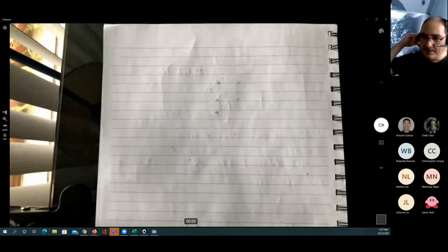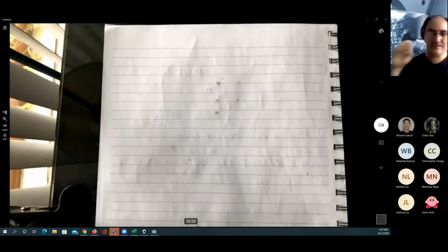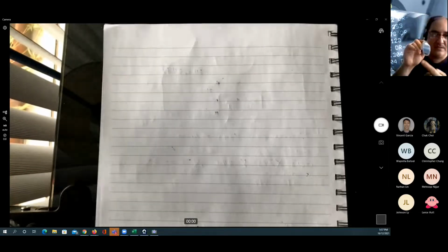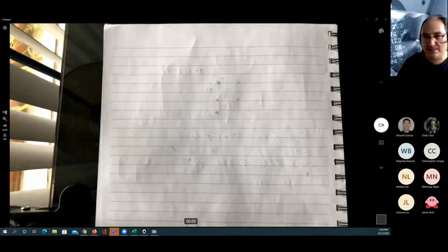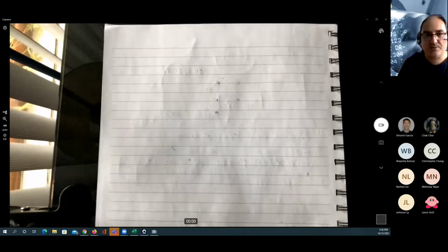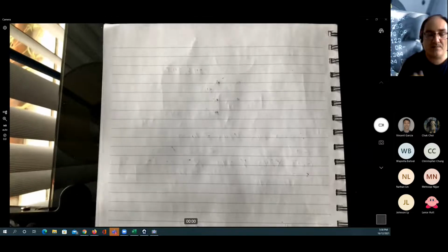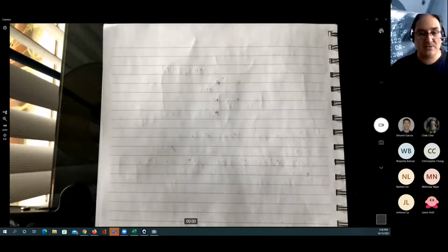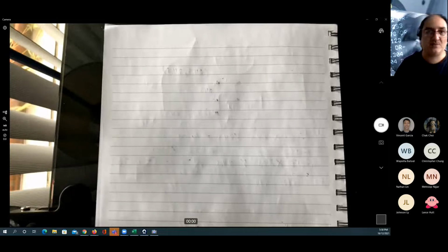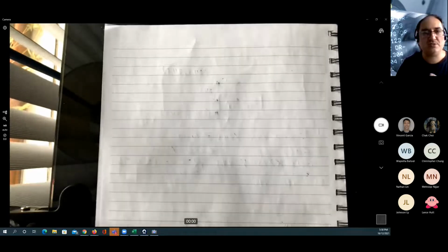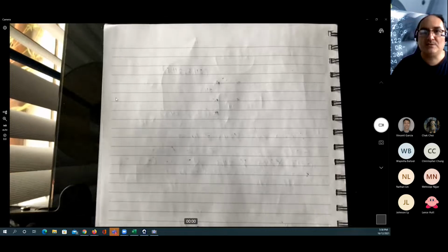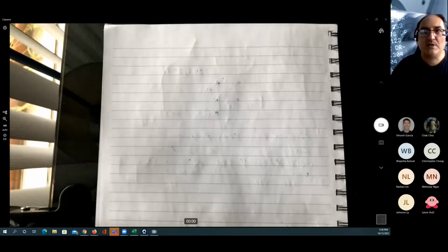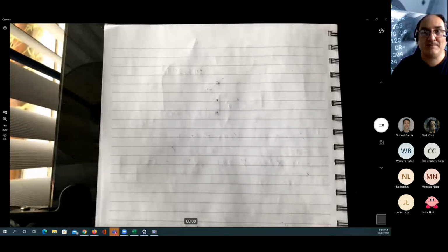For example, this shape is going to be symmetrical, but in case we have it offset from one side, at the high speed of the rotation, we're going to have a vibration. And this vibration is going to be too bad for the machine, for the cutting tool and the machine itself. So we always try to avoid having a non-symmetrical shape because this will cause a problem in the machining process.